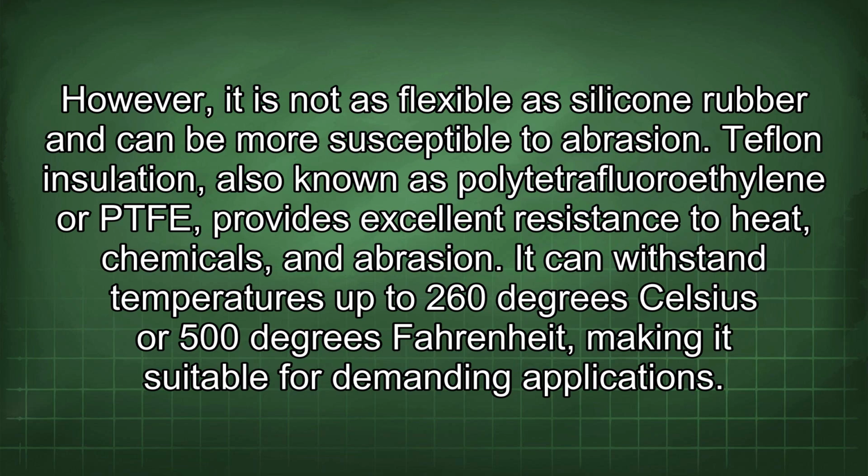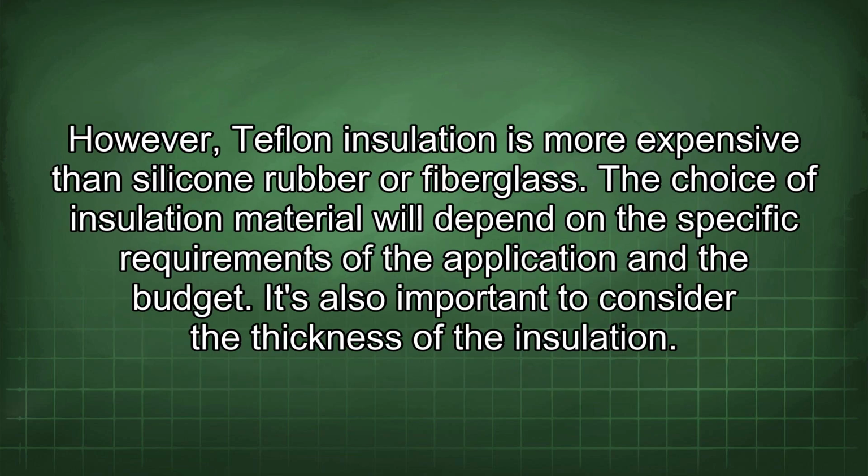Teflon insulation, also known as polytetrafluoroethylene or PTFE, provides excellent resistance to heat, chemicals, and abrasion. It can withstand temperatures up to 260 degrees Celsius or 500 degrees Fahrenheit, making it suitable for demanding applications. However, Teflon insulation is more expensive than silicone rubber or fiberglass. The choice of insulation material will depend on the specific requirements of the application and the budget.